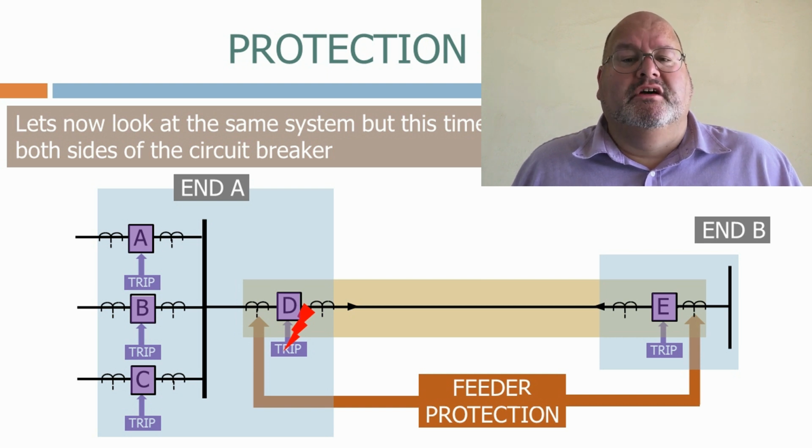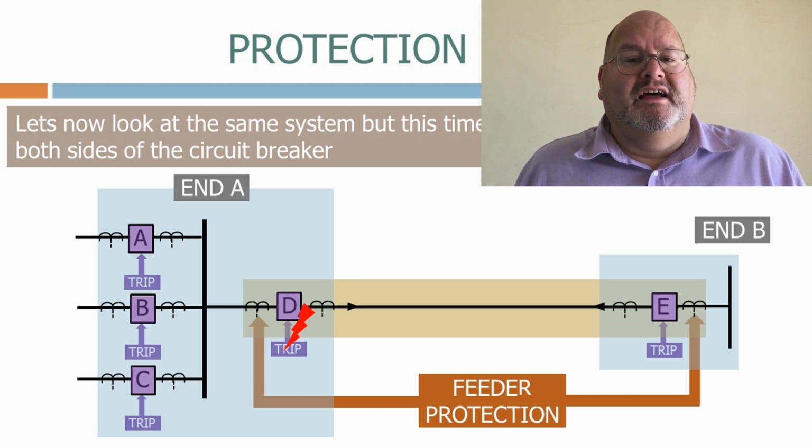Using protection zones formed by the current transformers allows us to provide a simple way of locating any fault that may occur on the network, and make sure that we only trip the minimum amount of the network necessary to clear the fault, i.e., achieve good fault discrimination.